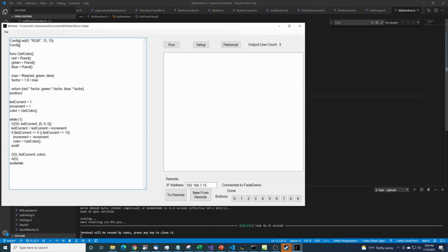So the way we do that, config button 0, make it a touch button, connect it to pin 32, which is what I have connected in the demo. And then this last parameter is a threshold. That essentially determines where the threshold is of identifying a touch or not identifying a touch. And that depends upon essentially how much metal you have connected and what you're touching and all that sort of thing. There's a debug setting that'll let you print that out so you can choose an appropriate threshold.